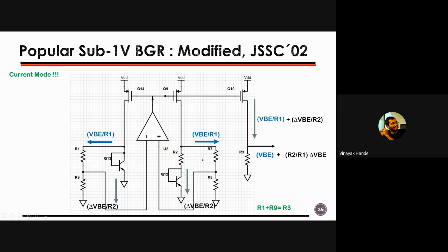I have not mentioned his name, but what Long has done is he has divided that resistor into two resistors connected in series, right? And connected to the PMOS-based voltage reference, right? As this voltage is down at the lower rail of the supply voltage, you can easily drive the PMOS differential pair with a high input common mode range, right? So this architecture is also quite popular.